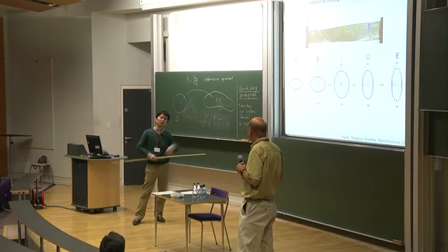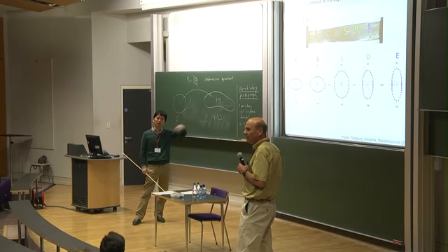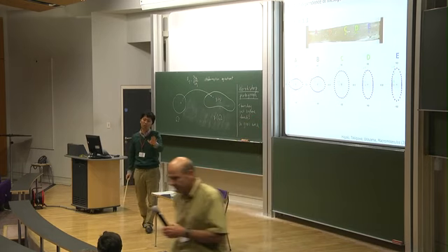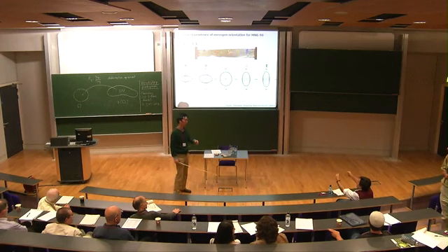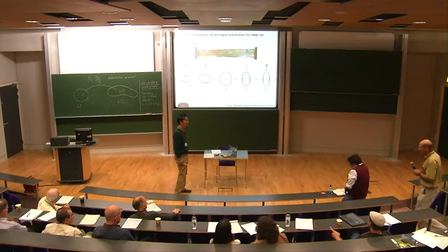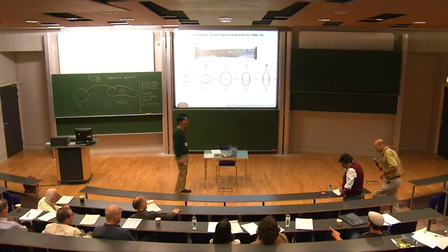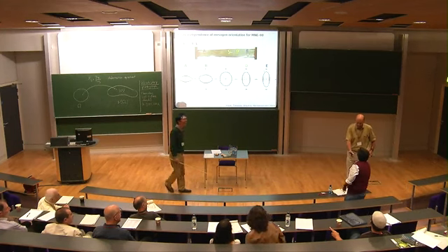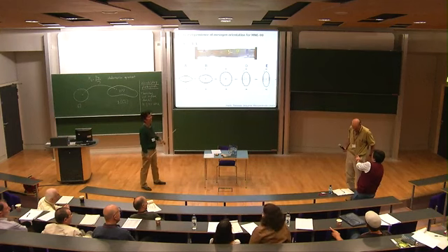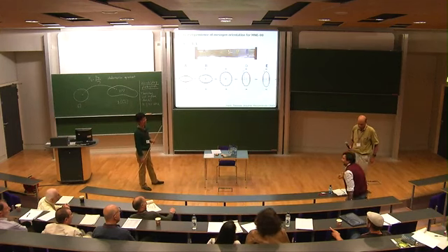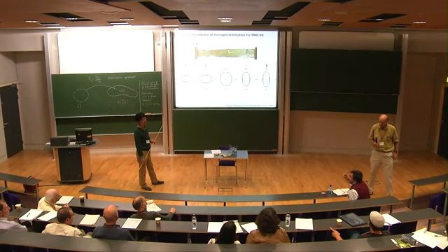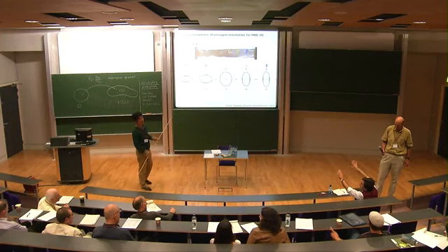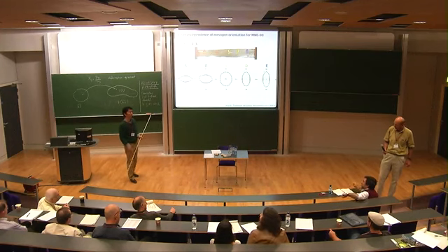I think in the final slide I will show the thickness dependence of the phenomena, but I think the wrinkling is related to this phenomenon here. Maybe I should stretch. And if you did that in a thin sheet, the critical region for the onset of the instability would be regions near the clamps, not in the middle, but near.